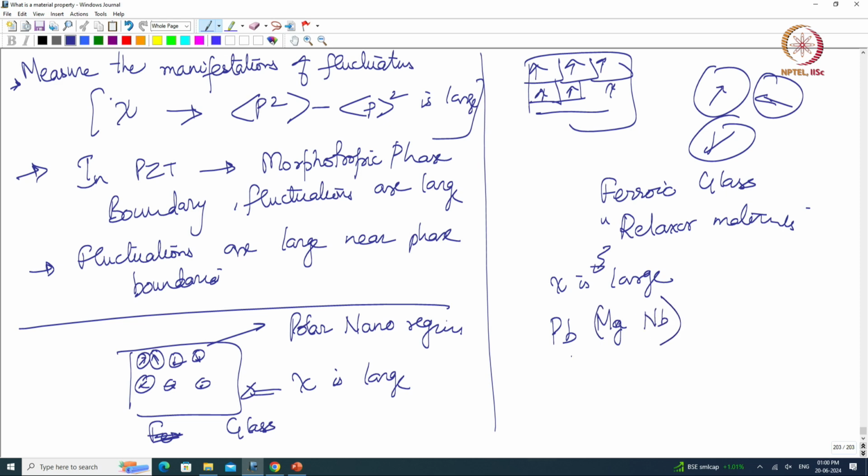In the same B site, this is the A site, these are all perovskite materials, this is the B site, 1 minus X, this is X, I have O3, and I can still alloy it with lead titanate. Lead titanate itself will have its own polarization, with 6 different polarization directions. Here, when I alloy it with manganese and niobium, it just becomes too many different polarization directions.